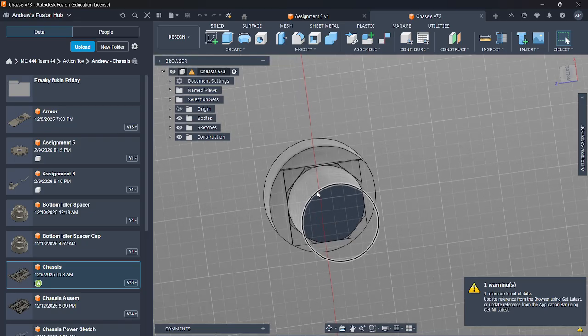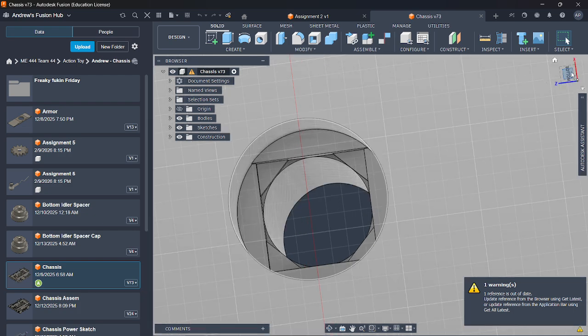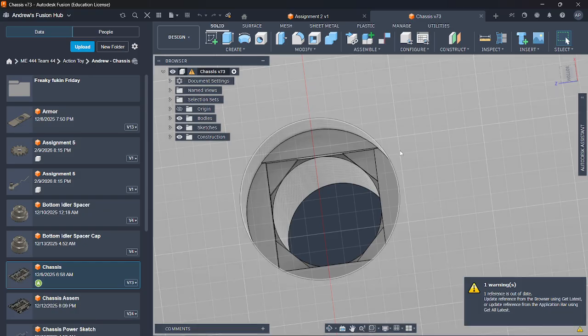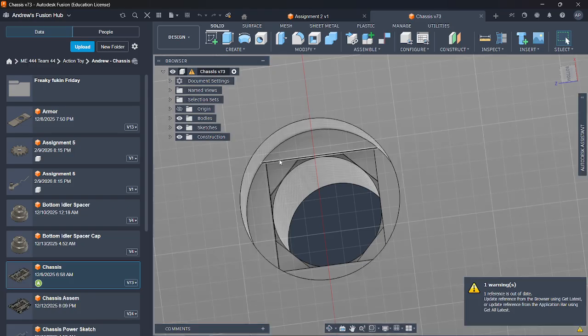So one of the things you can do is model things in certain ways to manipulate the slicer. In this case, there's a progressive stack of overhangs. You can see here, there's this feature that goes across, and the printer will bridge straight over, right? So it can do a straight overhang or a straight bridge pretty easily. So you can stack them progressively. I had it going this way, and then the next layer, it went this way, and then the last one is here. And that builds up an area that it can print for it to print this circle right here. So that's a little trick that I picked up along the way.